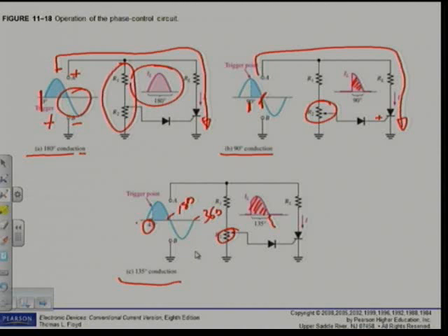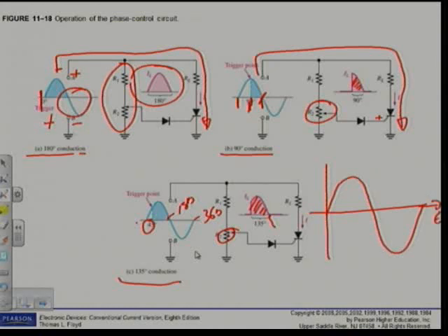All right. That is basically what we call phase control. That means I can control the amount of power to my load. One important thing here, with a circuit like this, we can only control basically from 0 to 90. That means the control can only take place from there to there. All right, let me make another drawing. We look at this, we can only control from 0 degrees to 90 degrees.